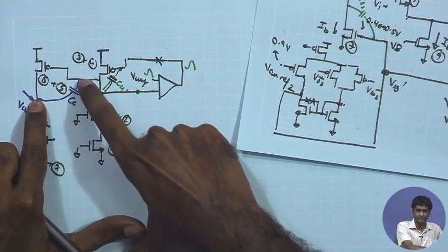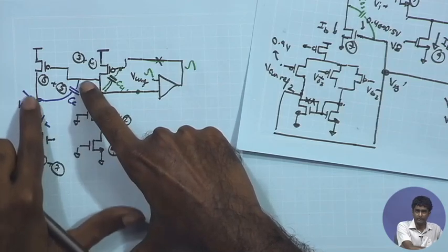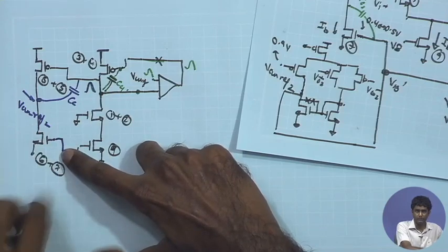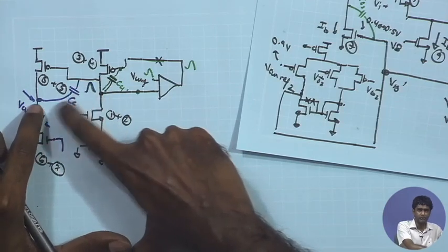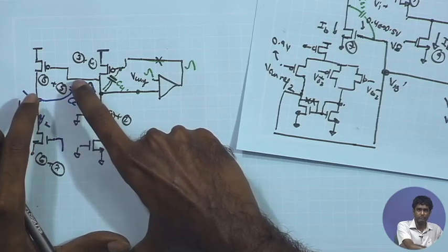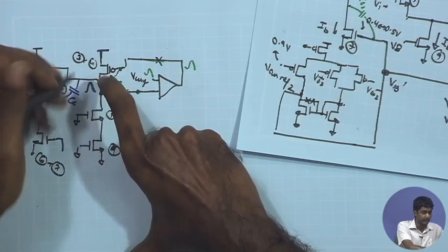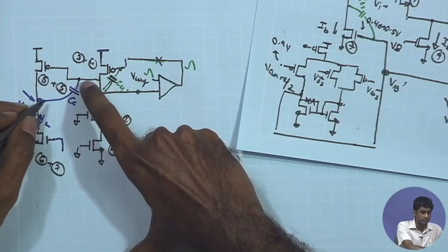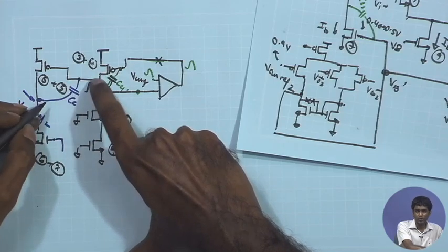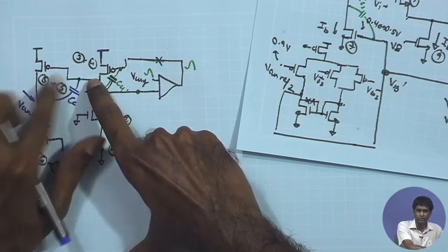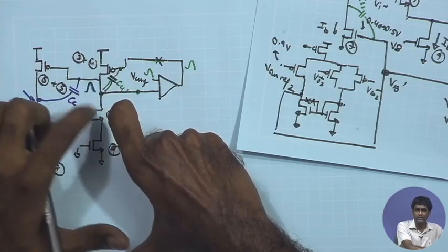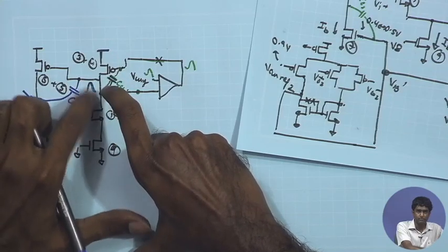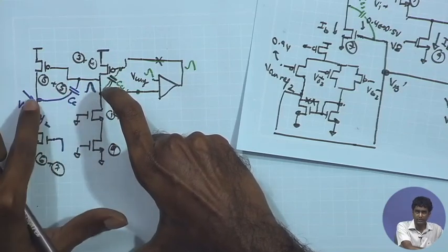Therefore, even if you change a signal over here, there is no fluctuation because this is being dictated by the common mode feedback loop of the second stage. As a result, the CC will not experience any multiplication. CC would experience multiplication for the common mode only if any excursion in this signal would produce a much larger excursion over here. Only then does the Miller multiplication come into effect, because a small change in voltage over here produces an overall terminal voltage across the capacitor which is much larger, and for that you need to supply much larger charge on this side. But that is not happening because even if there is a small signal excursion over here, this is remaining constant.